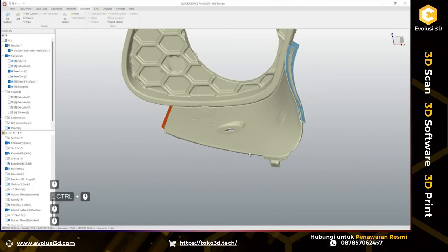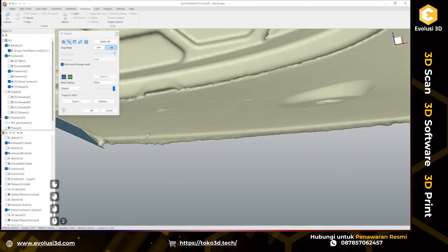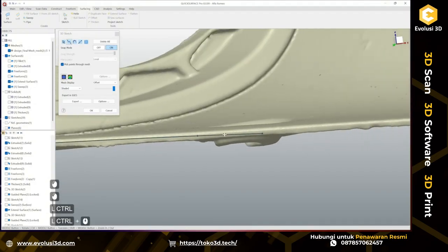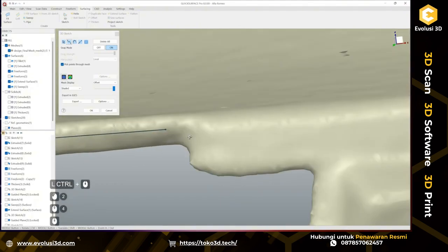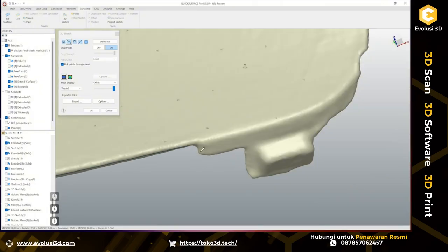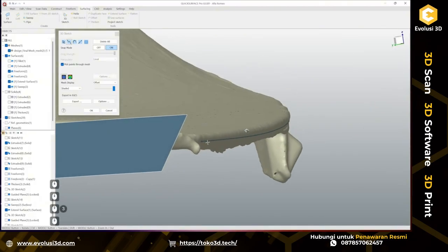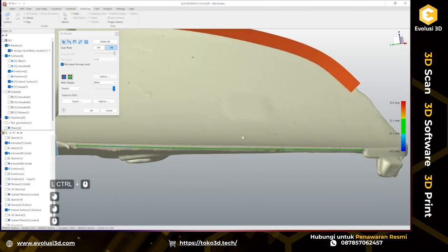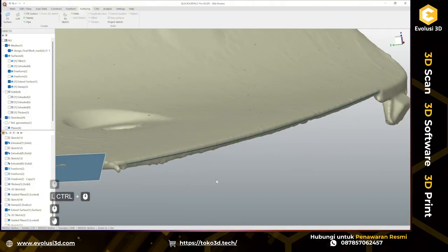So now at this point, I can proceed to the front edge here. So I'm just going to create another 3D curve. Say something like this. Not to go over this corner. This corner I'll have to recreate a different way. So currently I'm focusing on, say, main surfaces. And deviation control shows it's good enough. So let's accept this one.